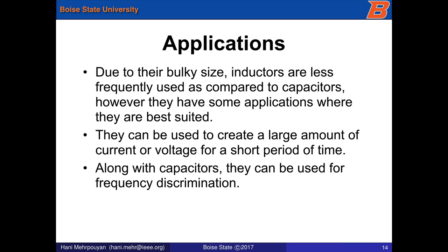What they are used for is they're used to design filters. Unlike a capacitor that is an open circuit for DC, inductors are a short circuit for DC, but then they're an open circuit for high frequencies. So you can use them to design low-pass filters in conjunction with a resistor, or you can use them in conjunction with a capacitor and a resistor to design a band-pass filter. And that's what is used inside, for example, your radio to eliminate the radio stations that you don't want to listen to, and only listen to the radio station that you're interested in.